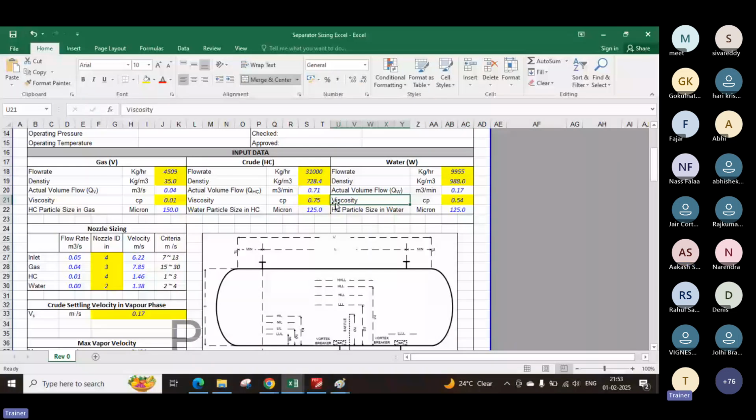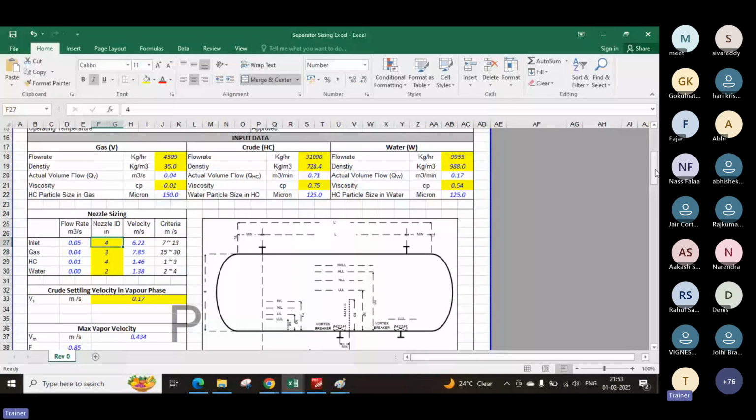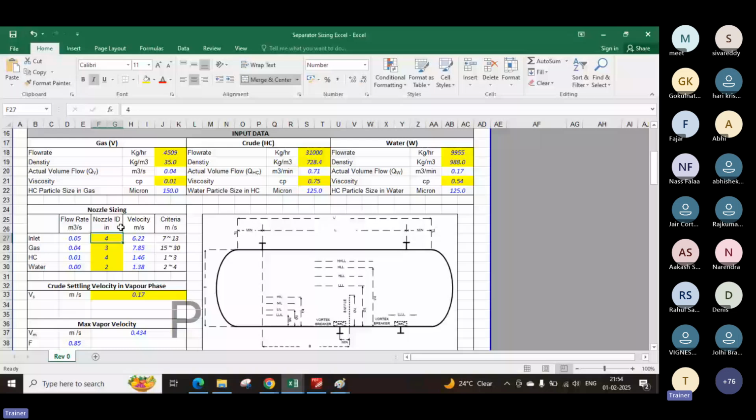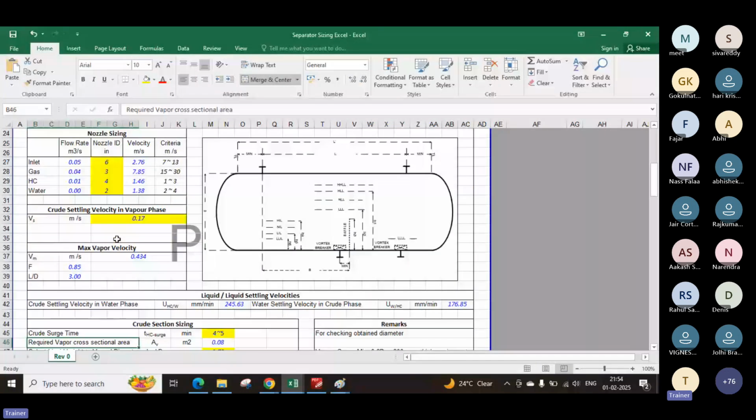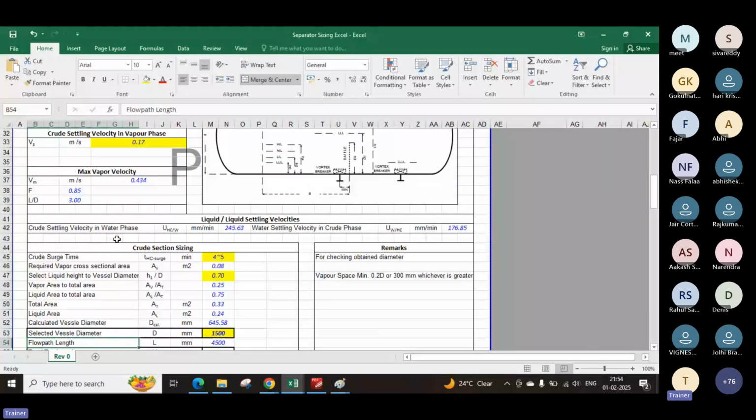Okay. So what we generally do is define these yellow parameters. In actual sizing, we define this typical inlet line. I just consider, say, 6 inch. Then I will come to know what velocity sizing you are giving. At the same time, it will give you rho v square values as well based on these sizes. At the same time, I will calculate or force some values, so I directly give values and the program will tell me the minimum sizes I need to have.